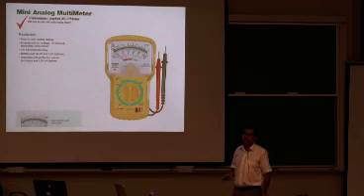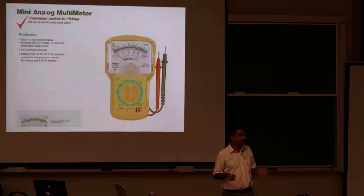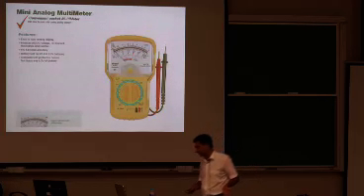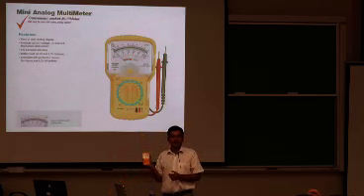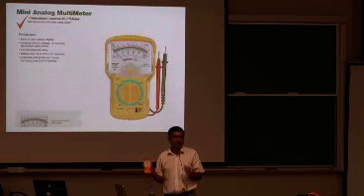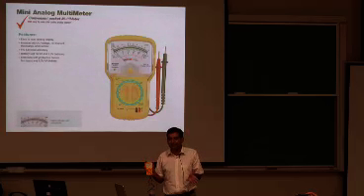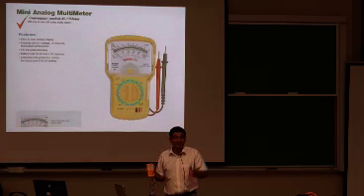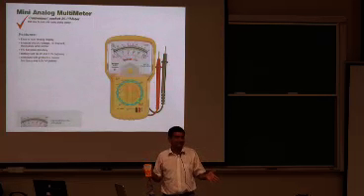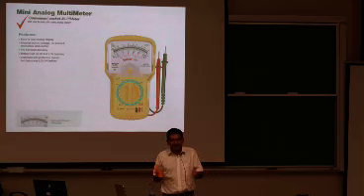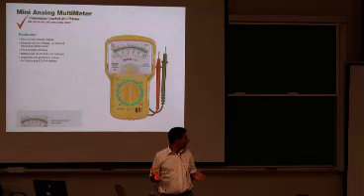Okay, now let's try measuring the voltage or EMF of a battery using an analog meter. Now this is an analog meter, right? It looks more complicated, and remember, digital multimeters are not necessarily more accurate than analog multimeters. And another point that you might have noticed is that an analog meter can actually be more precise than a digital instrument because the uncertainty is smaller.